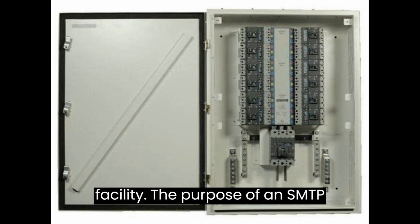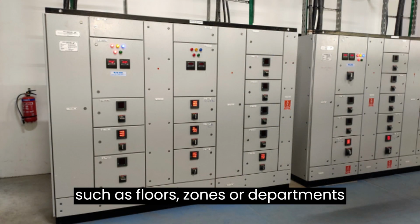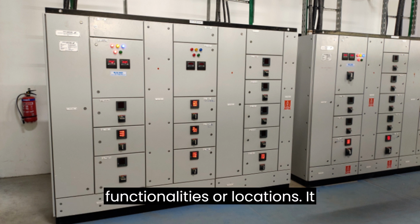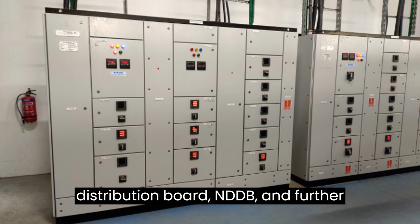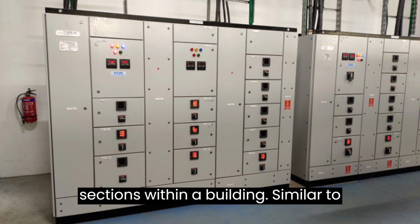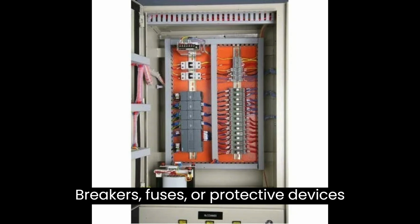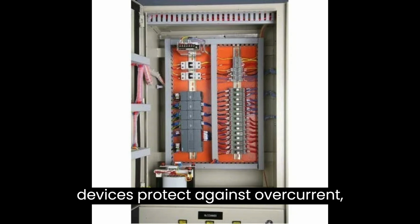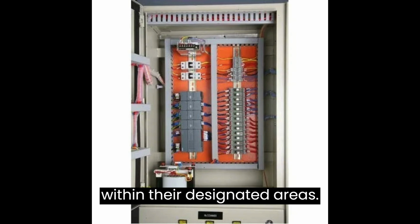The purpose of an SMDB is to divide and control the electrical supply to different parts of a structure, such as floors, zones, or departments, by grouping circuits according to their functionalities or locations. It receives electrical power from the main distribution board, MDB, and further distributes it to specific areas or sections within a building. Similar to the MDB, an SMDB contains circuit breakers, fuses, or protective devices that control and safeguard the electrical circuits connected to it. These devices protect against overcurrent, short circuits, and electrical faults within their designated areas.